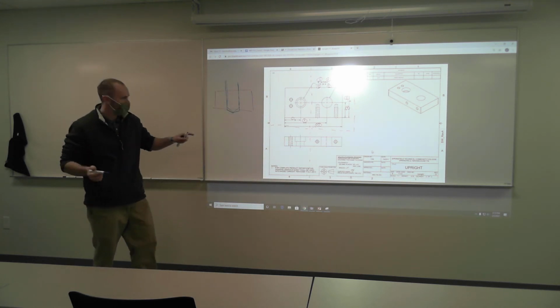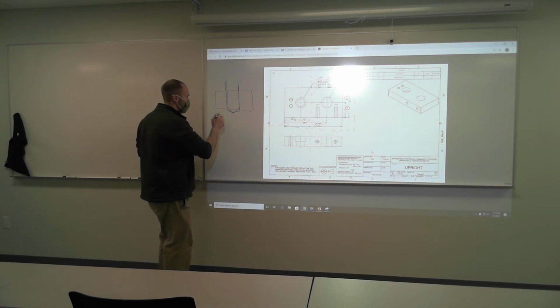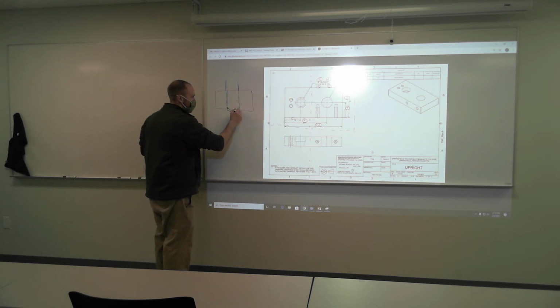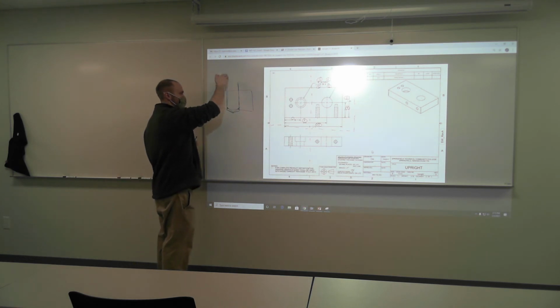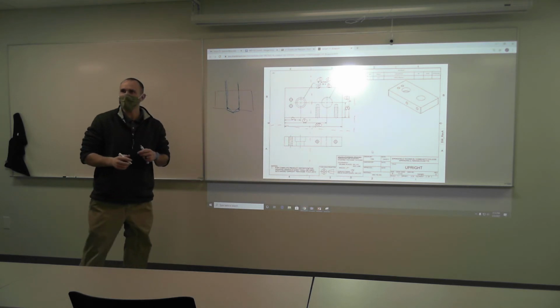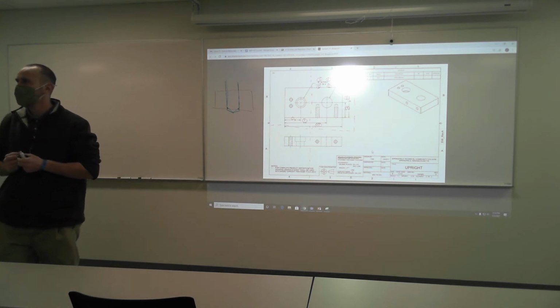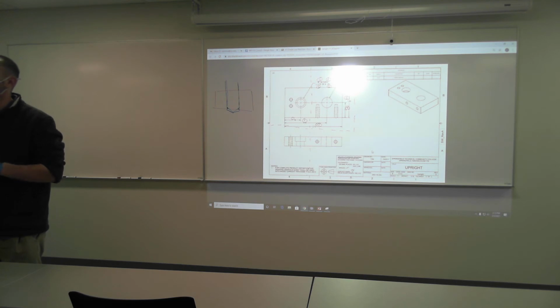Well, the problem is when you have a misalignment like this, you didn't actually go all the way through. However, when the human picks this up and looks at it, they say, I can see through that, that does actually go all the way through. I don't care what it looks like, I want to make sure it functions. So that's why we check the through condition.